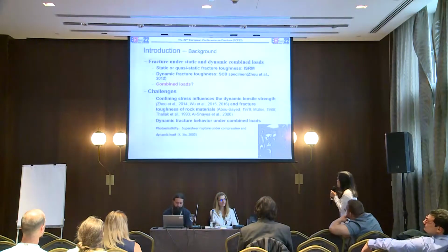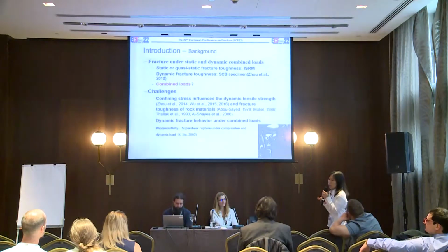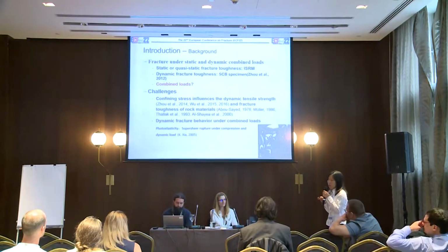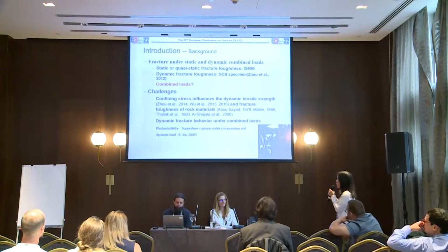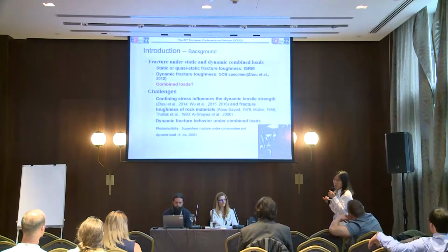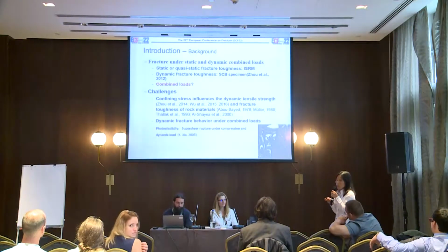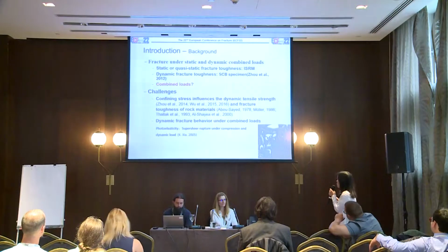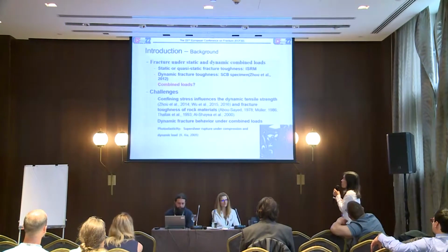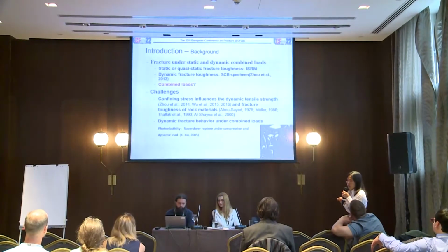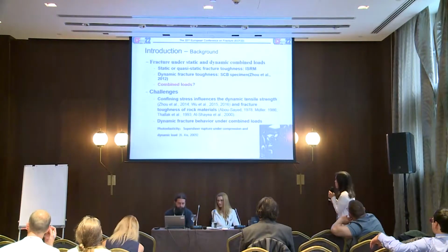And there are 2 challenges for combined load fracture. First, the confining stress influences the dynamic parameters, such as the dynamic tensile strength or the fracture toughness of rock materials, so the testing method may also be quite different from the single load.